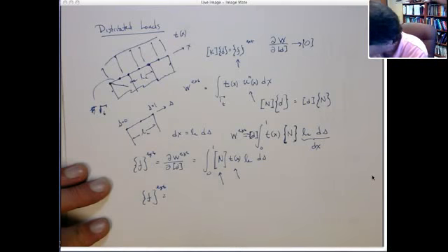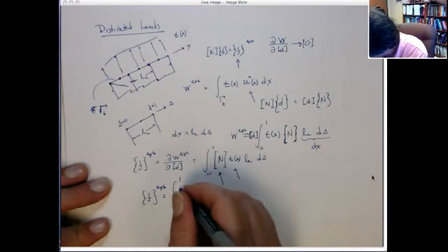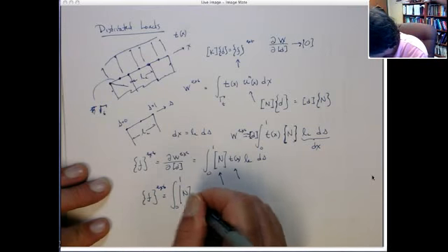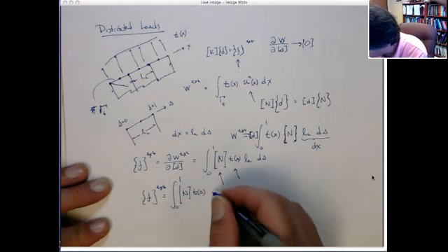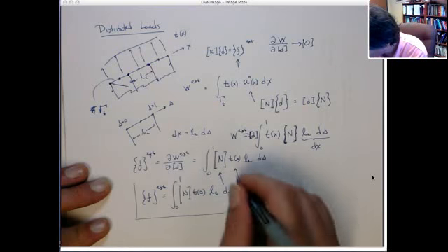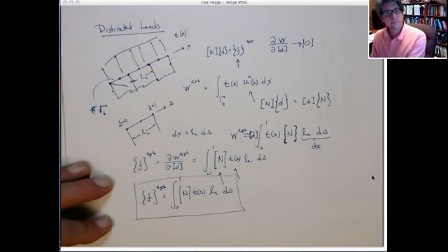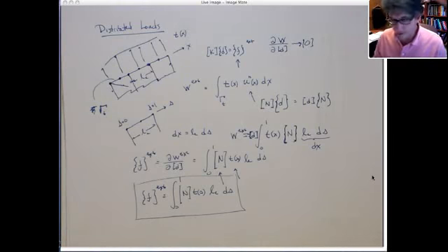The external force is equal to the integral 0 to 1 of the shape functions times the given traction, and actually that really should be in terms of s now, times the length of the edge, ds. Okay? That's what we're going to use. All right? And actually, maybe I'll pause the video here and then I'll pick up and do an example in a second, okay?